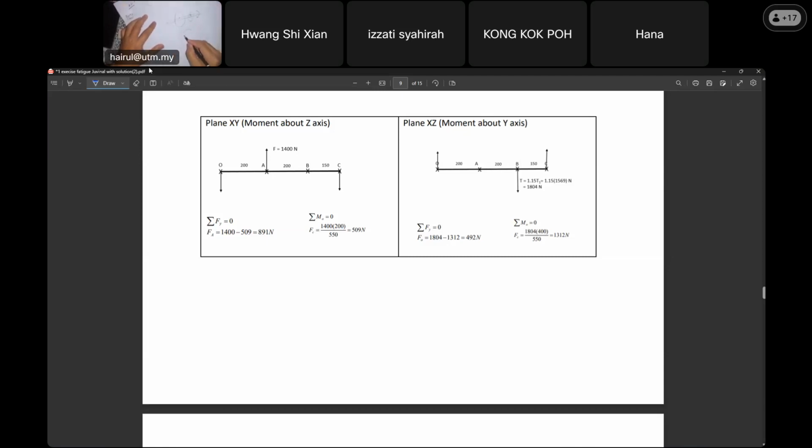Since section B is critical, up is tension, then as the shaft rotates it goes to compression, tension, compression, but the value is the same. At the top, bending stress is a positive value, but when it goes down it is compressive stress. Understand, class? Because the shaft is rotating, the element will face compression and tension by the same value.